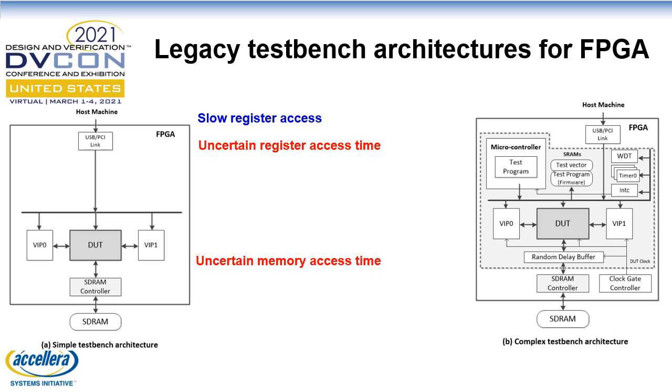Register access by the test program is very slow and its cycle-level behavior is unpredictable. Extra memory introduces uncertain bus latencies which limit the reproducibility of found issues. Once an unreproducible issue happens, considerable time is required to narrow down the symptoms with painful experiments on FPGA.